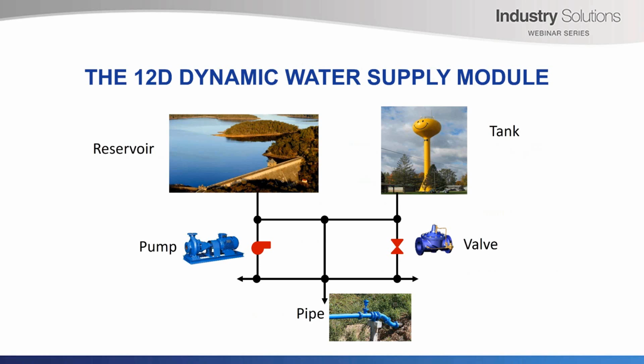The dynamic water supply module has all the features you'd be used to if you're doing stormwater design. So all of the stuff that's normally in the drainage network editor is present in the dynamic water supply module. So doing things like setting pit types and pit sizes and positions and orientation and interacting with the design strings so you can actually build the network, lay it out and build it, are all standard components.